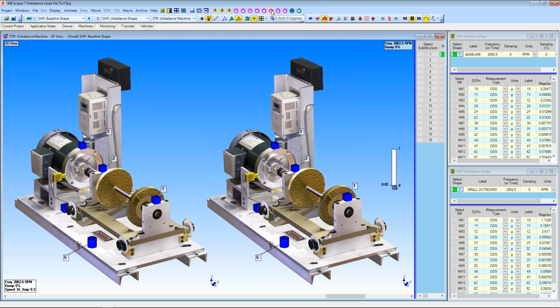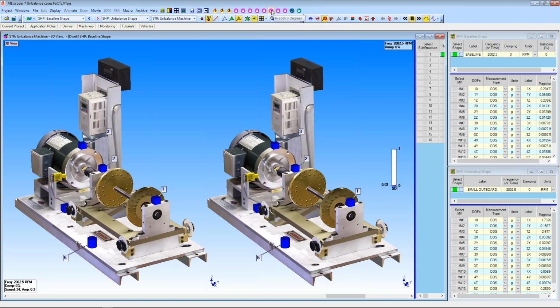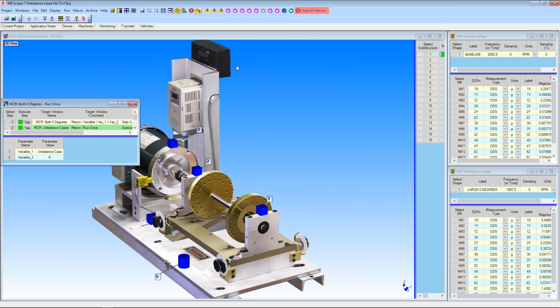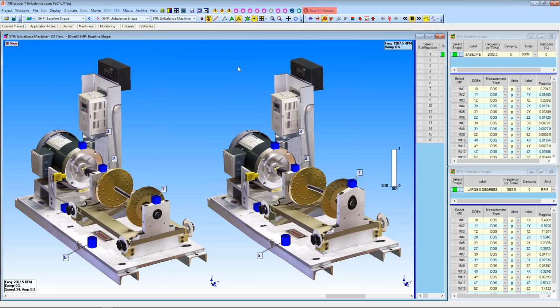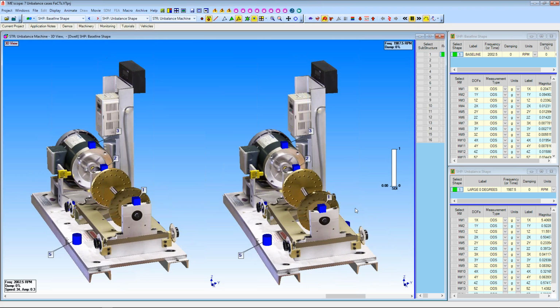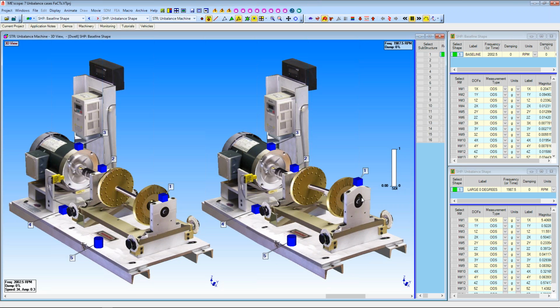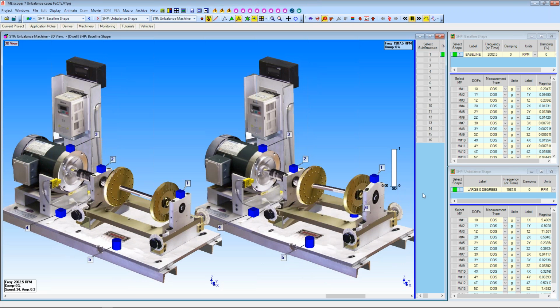Let's go all the way out to this one here, which is the worst case. It says both wheels have unbalance at 0 degrees. So we put a little unbalanced screw on both of the rotors and they're both in the same position, unbalanced. So let's just go ahead and press that. Again, that's going to pull up that data, and now you can see that the SDI is 0, and you can see the machine is deforming quite a bit on the outboard bearing block, because that's kind of the most flexible.